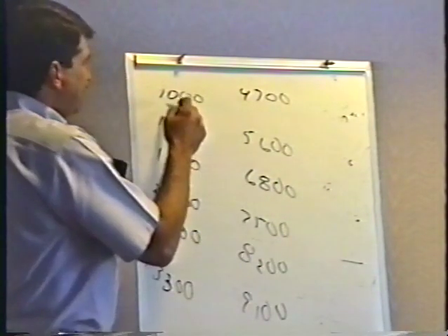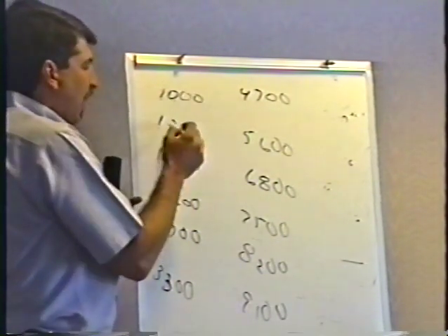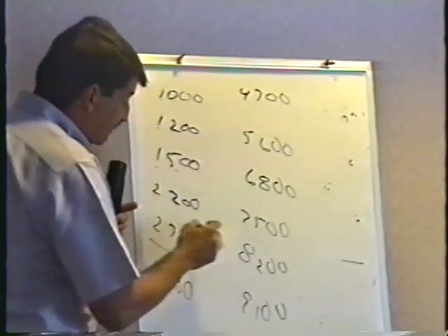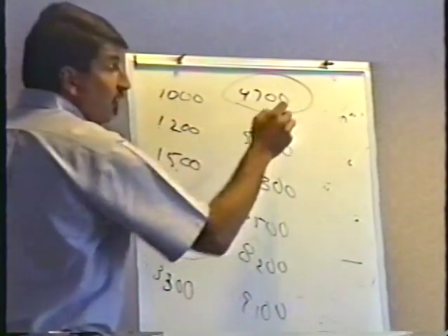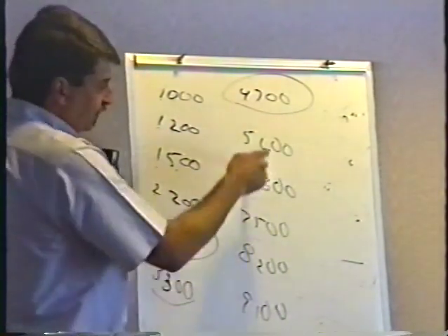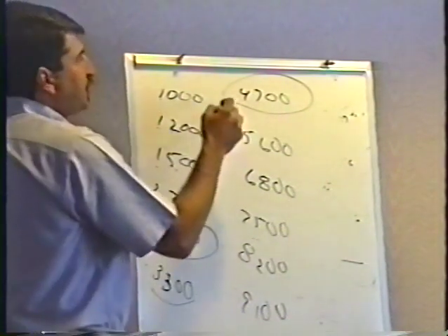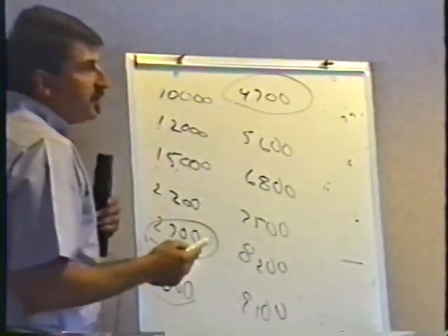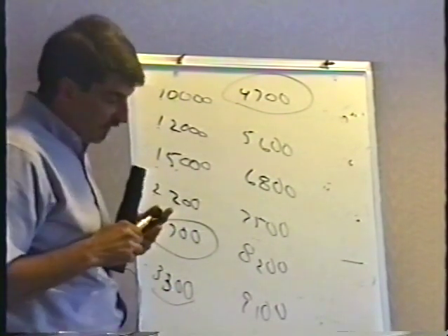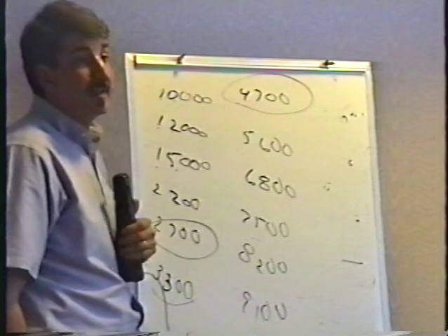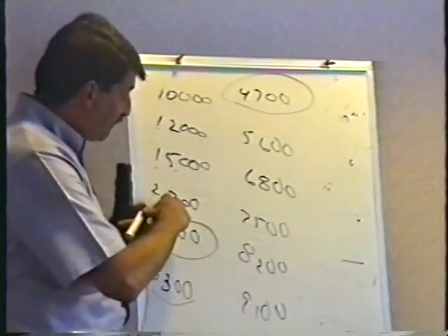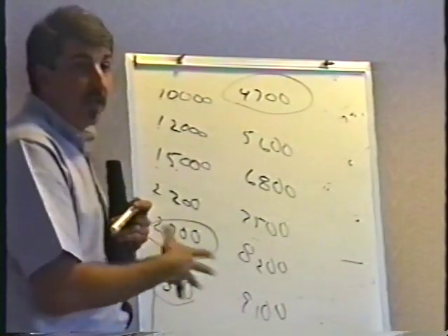So in other words, I see lots of brown, black, brown, red, brown, green, red, red, red, violet, especially common. So is yellow, violet. Very common. I see orange, orange, and so on. I see these combinations, and then we just change the multiplier band. So for instance, I see a brown, black, red resistor. Well, that's really familiar to me. That's a 1K. We use those a lot. But you hardly ever see 2K resistors. You see 2,200 ohms, you see 2,700 ohms.